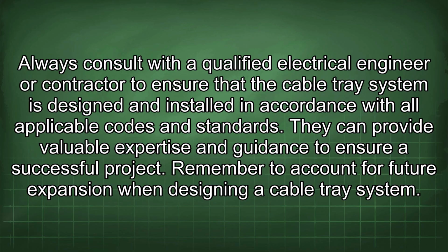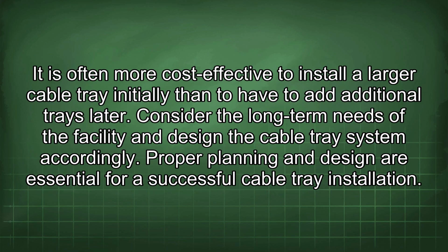Remember to account for future expansion when designing a cable tray system. It is often more cost-effective to install a larger cable tray initially than to have to add additional trays later. Consider the long-term needs of the facility and design the cable tray system accordingly.